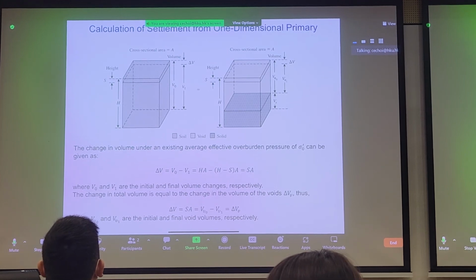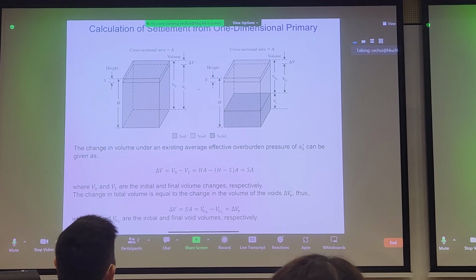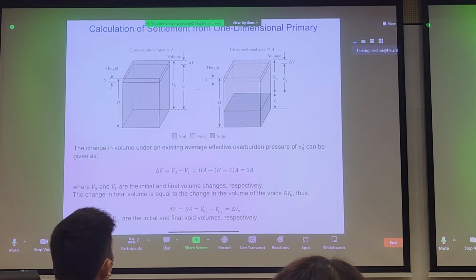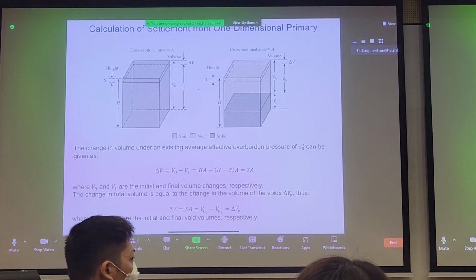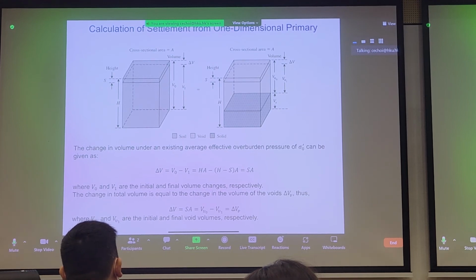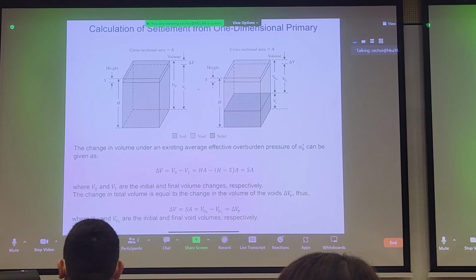Let's say you have a clay layer that's 10 meters thick. After consolidation, it becomes, let's say, 1 meter. You can calculate it. And then you know you have 9 meters times your area of sand replacement fill that you need. And it can be quite expensive. And then you might think to yourself, maybe I don't want to compress this so much. Maybe I'll put in some deep cement mixing columns, so I don't get compression. I don't need so much sand, right? So it really depends on how much compression and how much replacement you can handle.